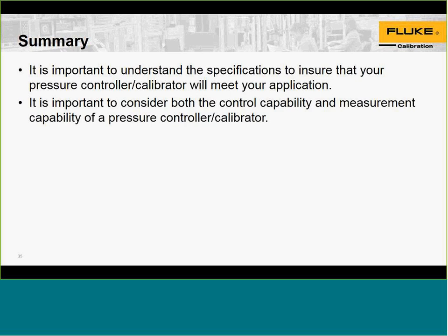It's very important to understand the specifications of the pressure controller to make sure it will meet your application, and basically, knowing the difference between percent of reading, percent of full scale, percent of span, and how the manufacturer interprets specifications for your application.